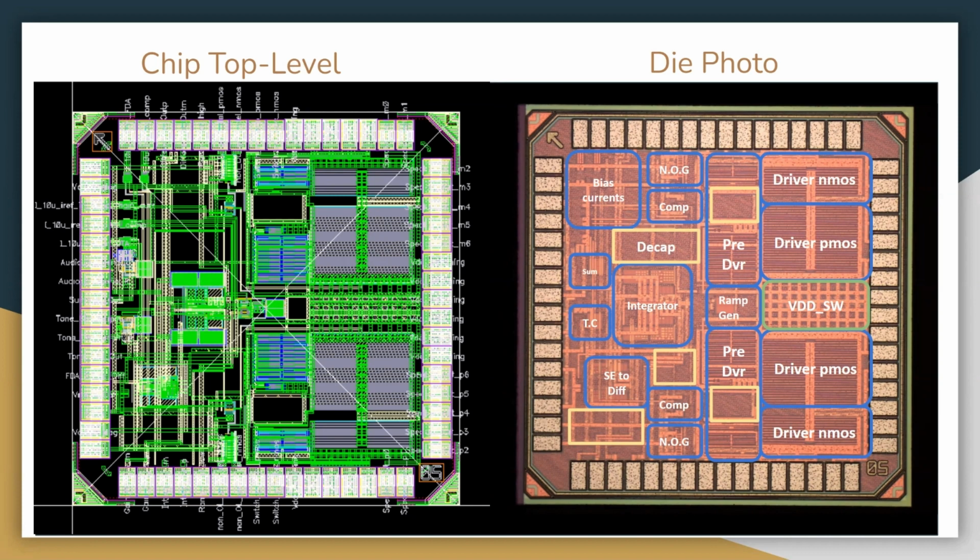We also added a lot of decap cells in our layout. The yellow boxes on the die photo show all the places we added decaps. The decaps help in reducing the switching noise injected in our system due to the drivers and PWM.